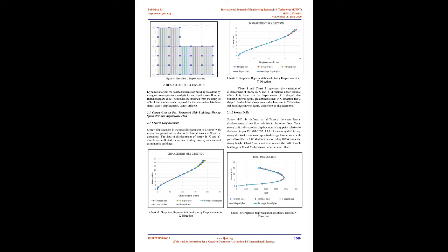D. Sectional properties of building. Beam dimensions for conventional structure: 300 mm x 350 mm. Thickness of slab for conventional structure: 150 mm. Thickness of slab for RCC and post-tensioned flat slab structures: 200 mm. Thickness of shear wall: 250 mm. Dimension of drop panel: 2000 mm x 2000 mm.